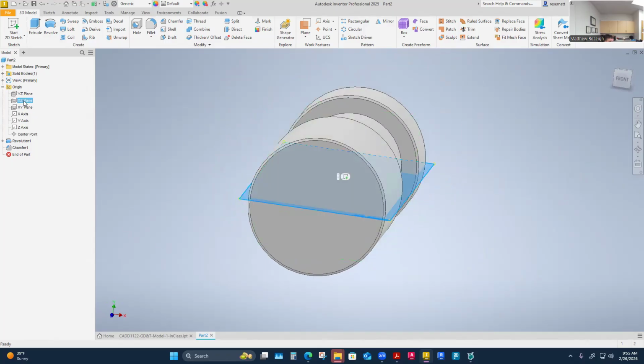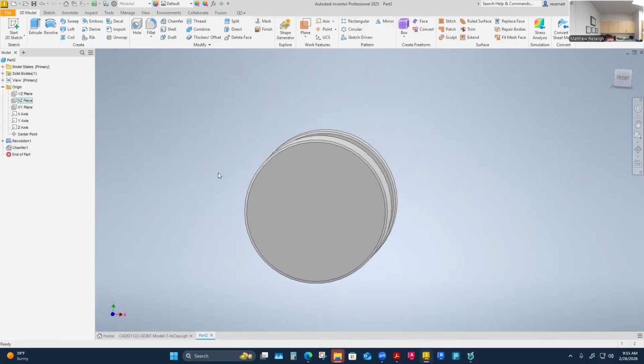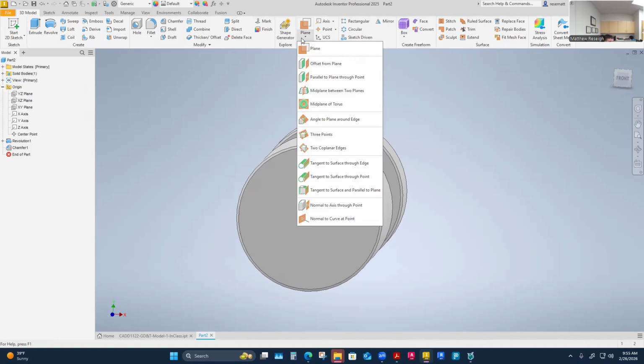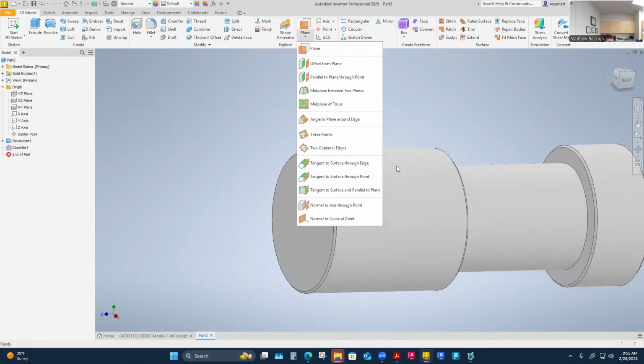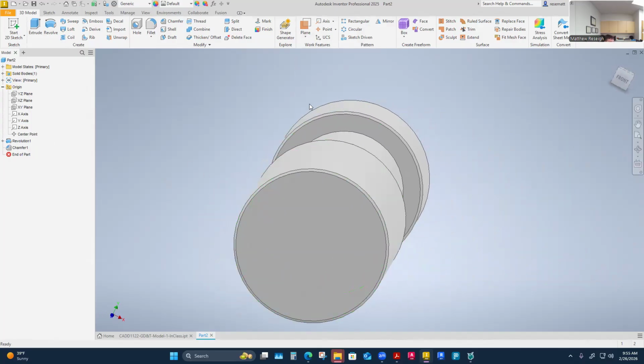Because I'm going to use this plane to draw on, which is an origin plane actually. If we don't have one there, then you could establish a new work plane to put this in. You could establish a new work plane that was tangent to this surface, and we've done that a couple times where I decide I don't have an origin plane that works well. Let me just establish a plane to sketch on. But you can also establish just a face. It's just, so this is really, I need to draw this way down through.